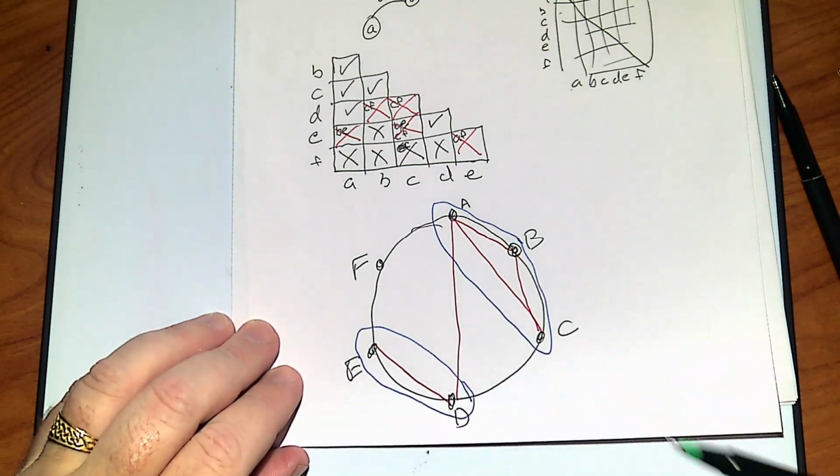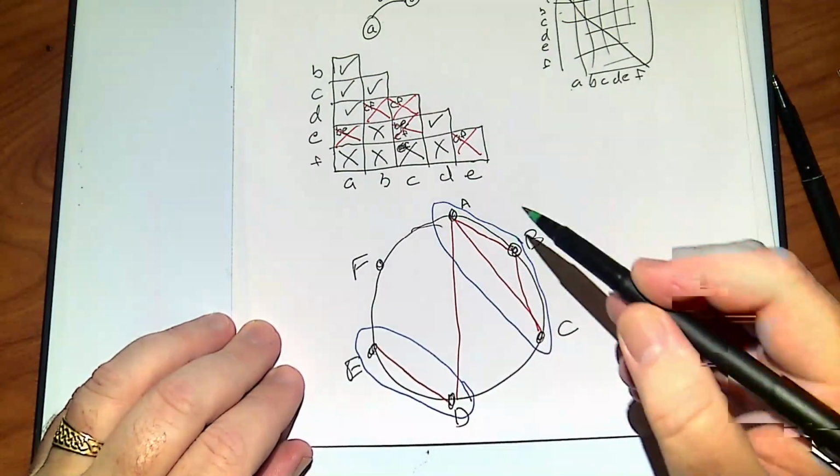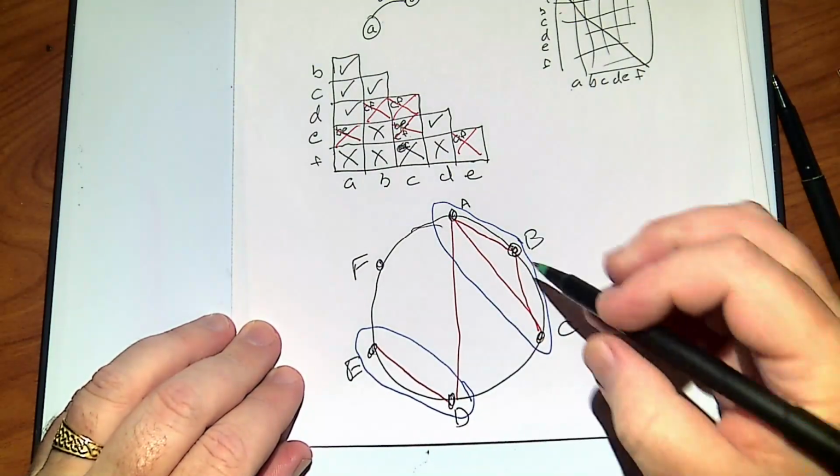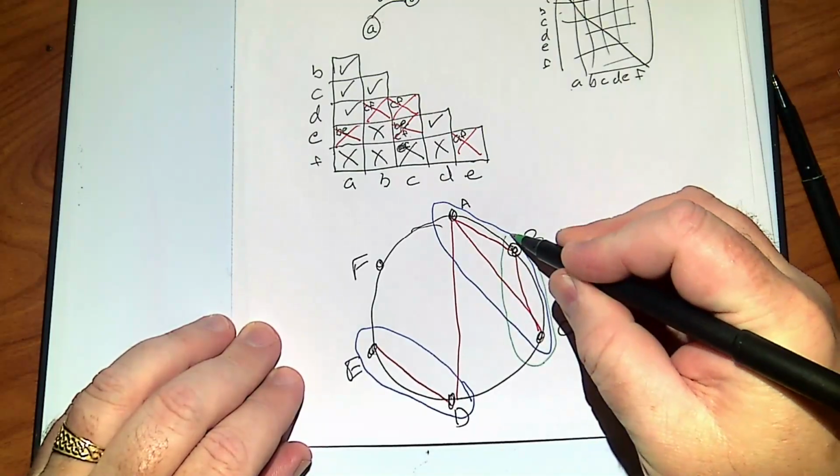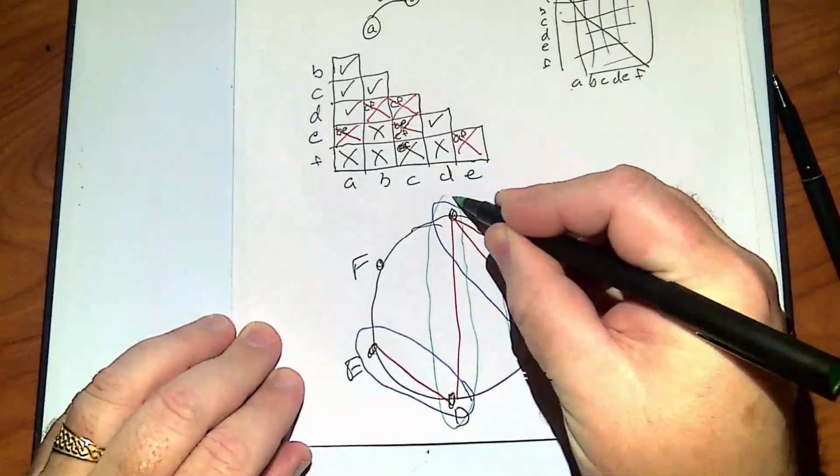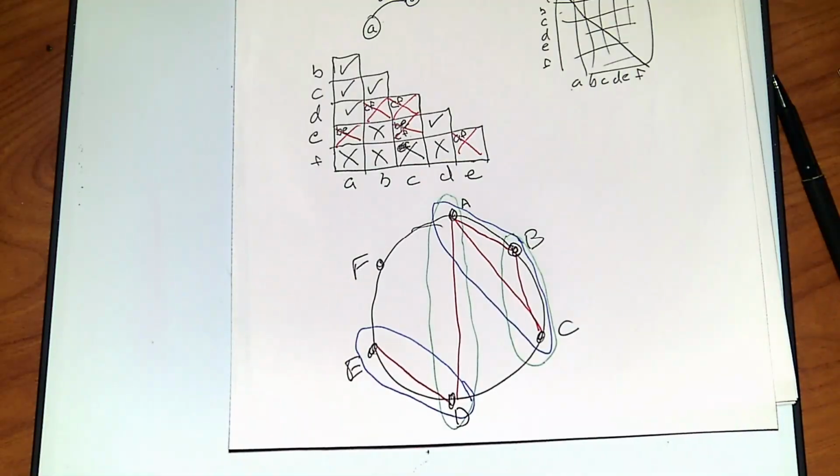So look, there are other ways we can do this. This is going to be green instead of blue. Could I merge just B and C and then merge A and D if I wanted? It's legal. Could I merge ADE? No, you can't do it. But we could do this, and maybe this ends up being easier for me on whatever state transitions I want. It might be better to merge BC and AD.